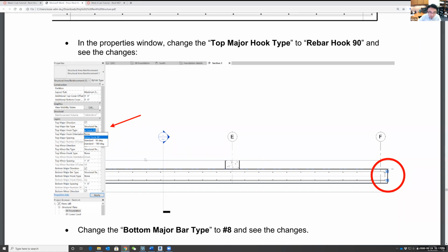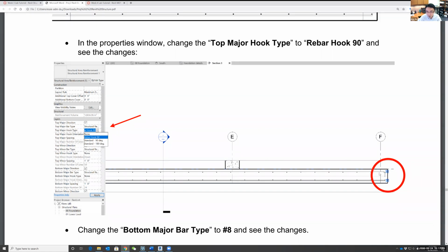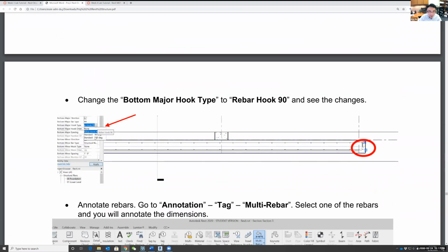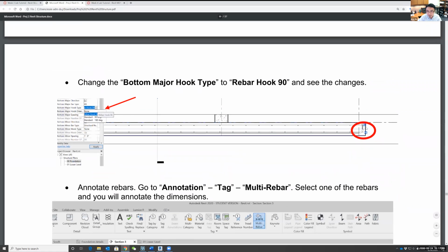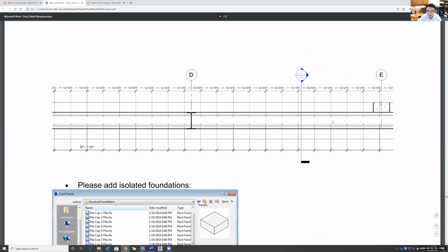Okay, anyway, so basically when we have the loads on the floor, it will bend this way, right? So for the upper part, we have a lot of tension. If you see the internal force, there will be a force in this way, so this hook is going to hold it up. We will have this hook here, and we also have a hook for the bottom. They actually use different angles, you will see from the tutorial, but that's straightforward. You just change the hook and you have the rebars here.